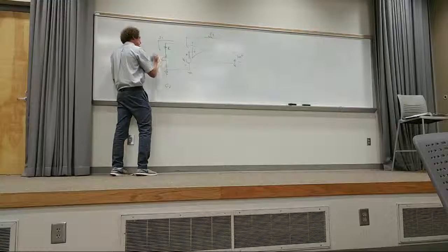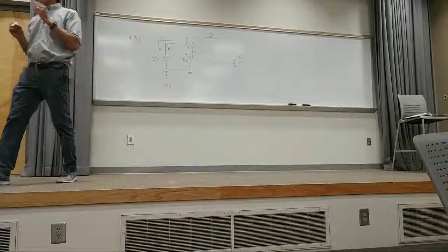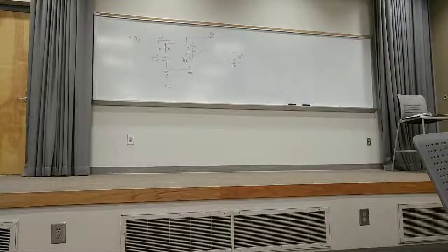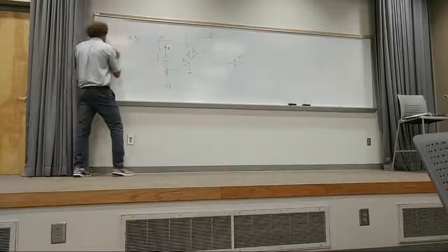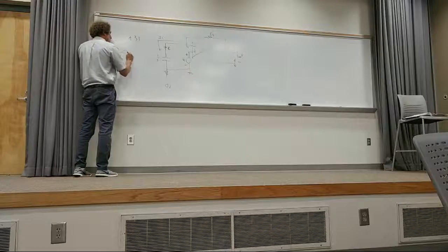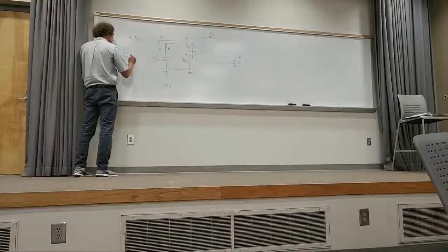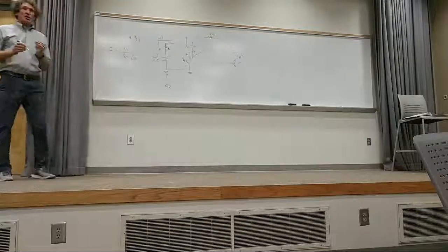This has an impedance of 1 over CS. Do you follow me, class? We're in the Laplace domain, so the impedance of the capacitor would be 1 over CS. Are you with me? Therefore, this current I1 here would be equal to simply V1 over R plus 1 over CS. There is no other capacitor. Do you all agree with me?